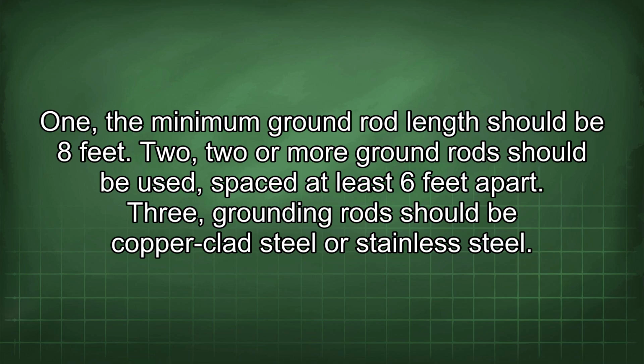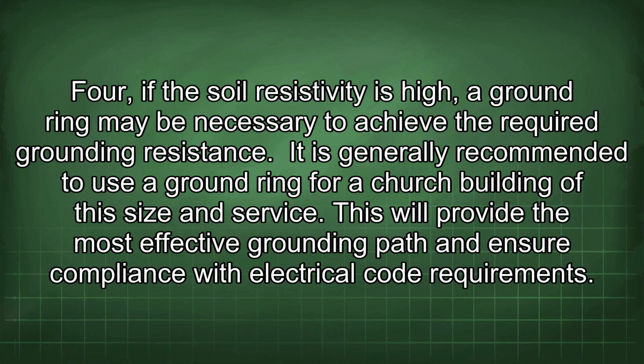3. Grounding rods should be copper-clad steel or stainless steel. 4. If the soil resistivity is high, a ground ring may be necessary to achieve the required grounding resistance. It is generally recommended to use a ground ring for a church building of this size and service. This will provide the most effective grounding path and ensure compliance with electrical code requirements.